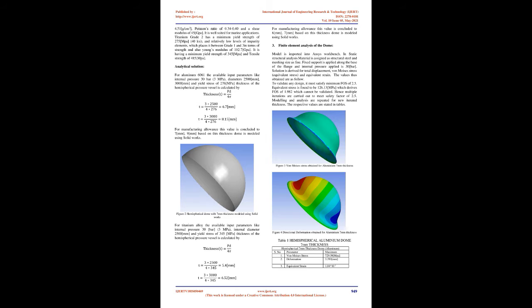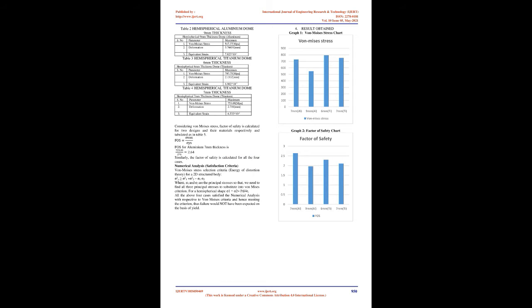2. Valuation for initial thickness. Material properties. Product standards define the limits for composition, quality, and performance, and these limits are used or presumed by structural designers. Aluminium 6061 alloy was originally called ALLOY 61S. It is a precipitation-hardened alloy and the most commonly available heat-treatable alloy. It has a density of 2.7 g/cm3, Poisson's ratio of 0.33, and a shear modulus of 26 GPa. It also has a good value of Young's modulus, which is about 68 GPa.